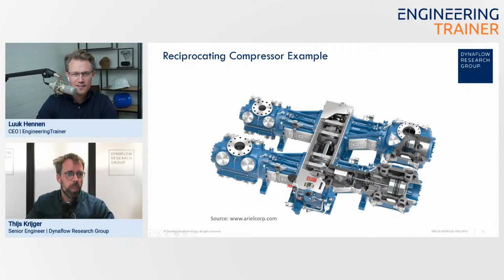Please, yeah. So it all starts from this central axis here, which is called the crank axis, and this will be driven by some kind of motor, either a diesel or an electric motor. So this rotates. On this side, you see there's a cut open part, which is a piston that's connected to that crank axis. And that connection point is a little off-center, so that when this axis rotates, that off-center connection point rotates and causes a linear motion of the piston.